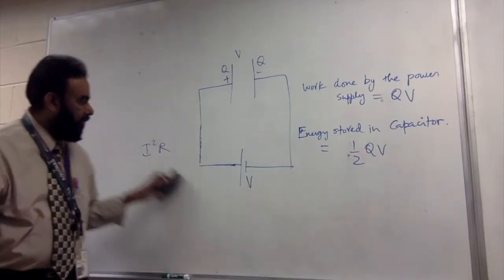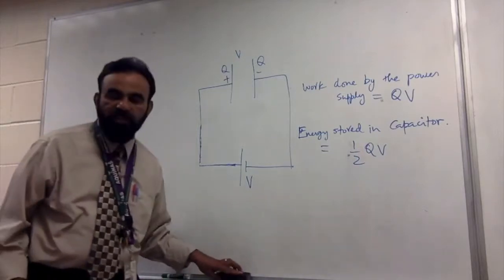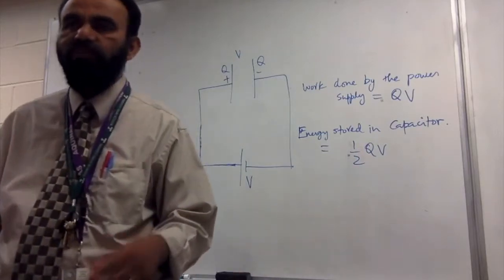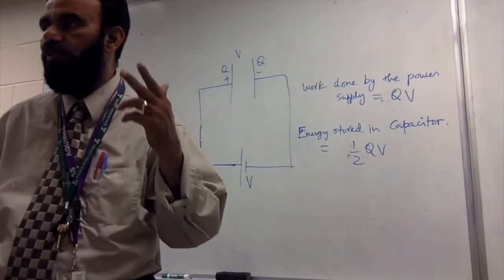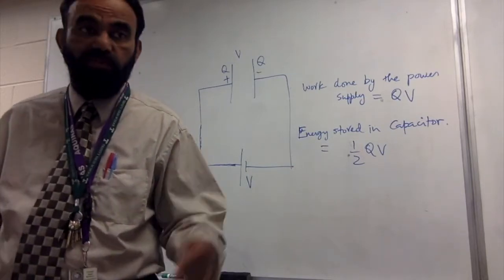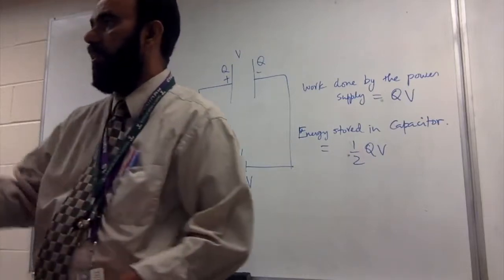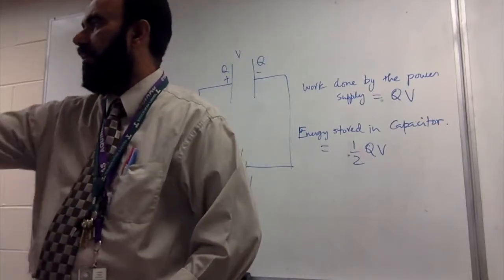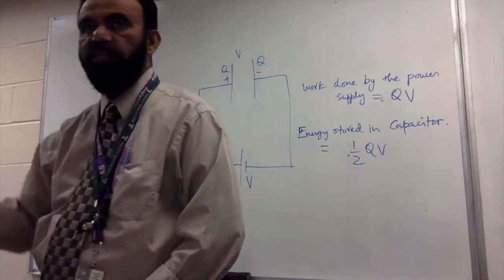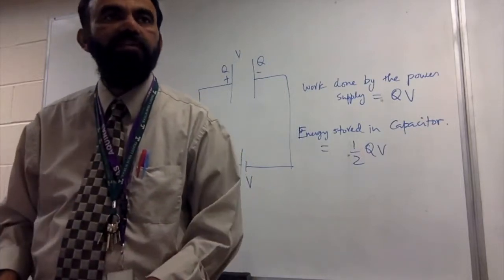Okay, so the heating effect, that's why when you want to use a proper extension cord, you have to know how much current is actually going to flow. So if you are actually going to connect one extension cord and multiple things, imagine I'm connecting with one extension cord that, and that, everything together, that's going to be overloading on the extension cord.